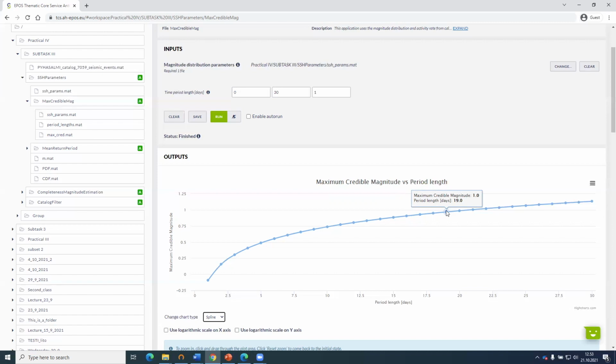And especially when we have more data, like 5-year data, and we are expecting the operation at the place to be more or less the same. For instance, at Pyhäsalmi mine, they extracted the ore in different parts of the mine. They didn't go in an order where they would start from the bottom, or start from the highest point of the ore body, but they took it from different areas of the deposit. And the reason for that was that if you give the rock mass some time to creep, it doesn't necessarily collapse when you extract the ore in the same area.